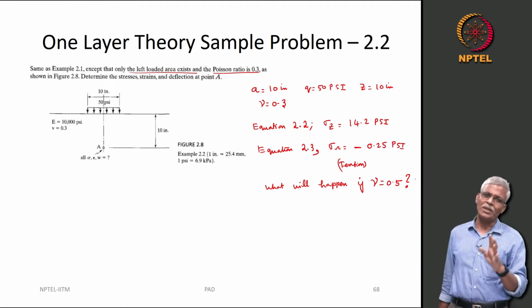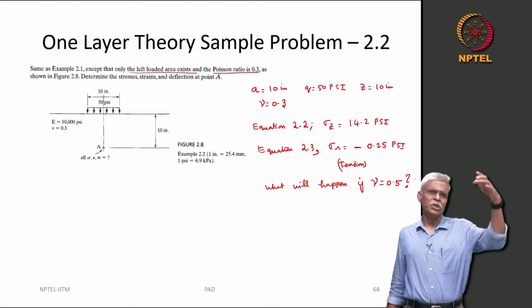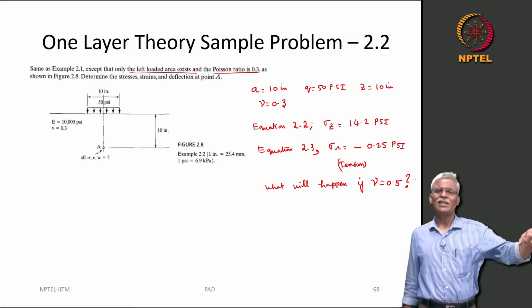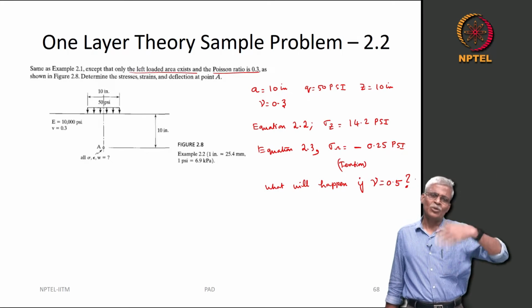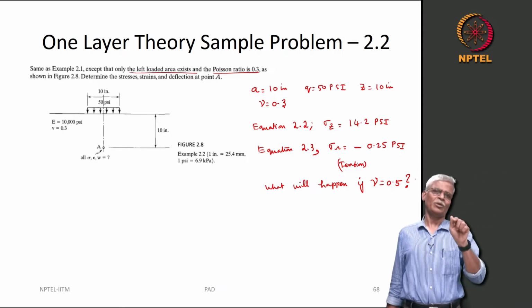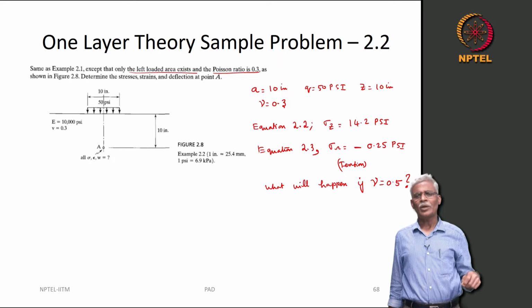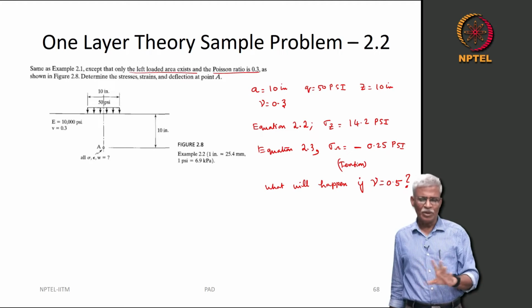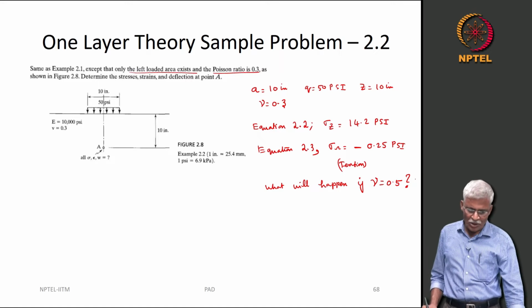Okay. So, just need to understand, because when you use Poisson's ratio of 0.5, you do not need to use this lengthy formula, you can just read it from the chart. And when you use the software, you do not need to worry about whether it is 0.3 or 0.5, because you just plug in the value and specify the coordinates you need, and you will be able to get all the solutions. So, this is what you need to really do.